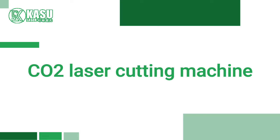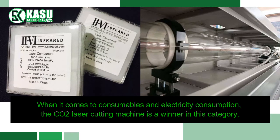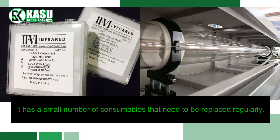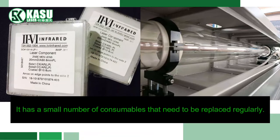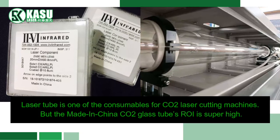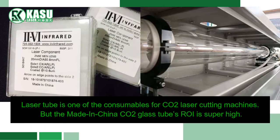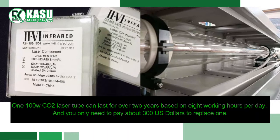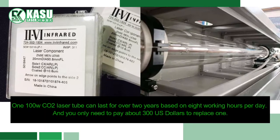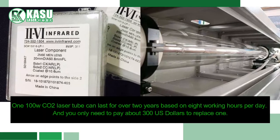CO2 laser cutting machine. When it comes to consumables and electricity consumption, the CO2 laser cutting machine is a winner in this category. It has a small number of consumables that need to be replaced regularly. Laser tube is one of the consumables for CO2 laser cutting machines. But the made-in-China CO2 glass tube's ROI is super high. One 100W CO2 laser tube can last for over 2 years, based on 8 working hours per day. And you only need to pay about $300 to replace one.